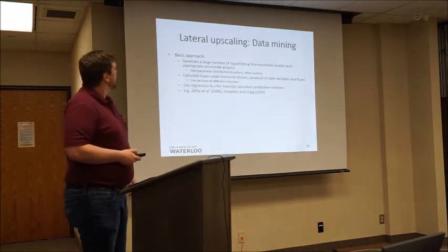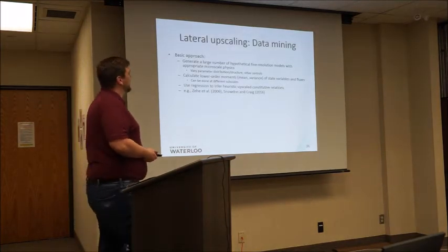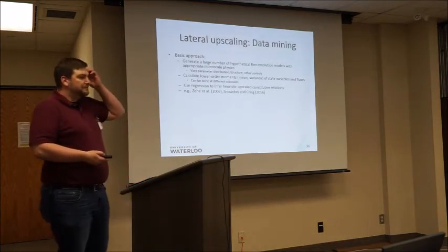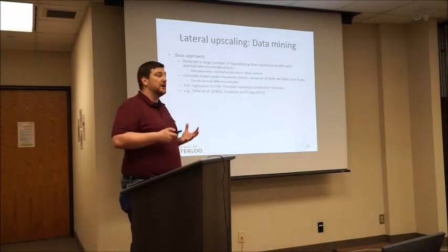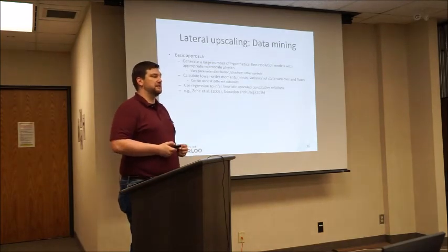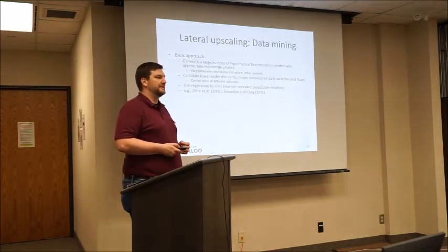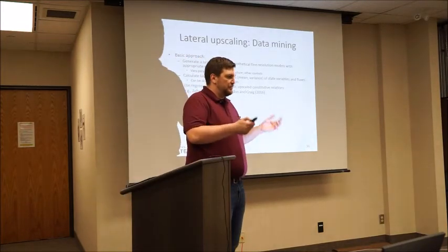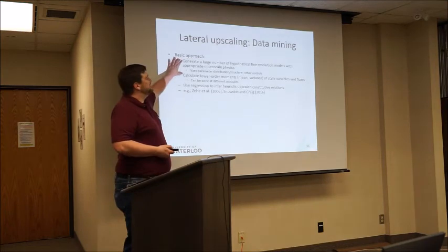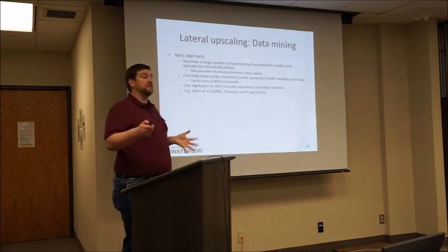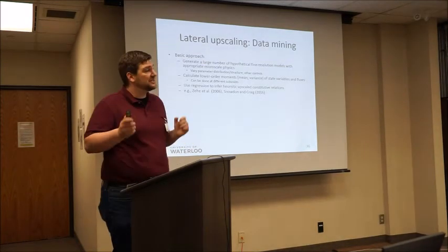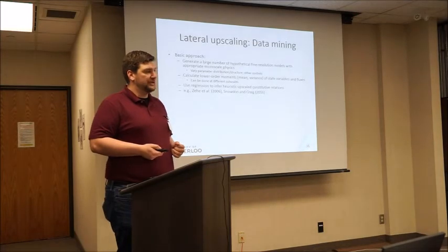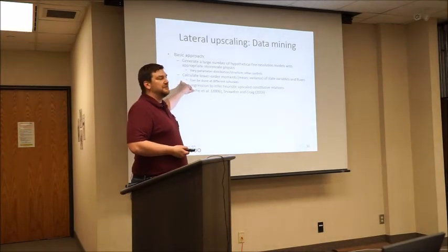All right. The other approach that we can look at is the data mining approach. The basic approach for data mining is we can build these complex, large-scale models with all the microphysics included. So we can build a HydroGeoSphere model with 10 to the 6th nodes and Richards' equation, groundwater flow, all that stuff. We can build a hypothetical toolbox, and we have complete control of all the parameters. So we can try to learn about how systems upscale by monitoring 3 or 4 watersheds, or we could monitor 10,000 hypothetical watersheds to look at what are the controls on upscaling.